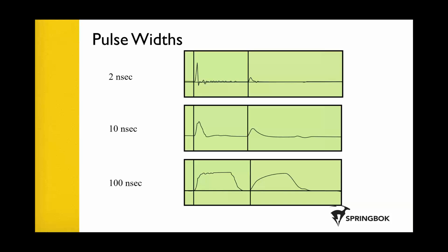If I give that rope a lot of energy, it's going to go a long ways, right? Versus if I give it just a tiny flick of the wrist, it doesn't go as far. So you could say that your larger pulse widths are for going longer distances or for testing longer lengths of cable, and your smaller pulse widths are for testing shorter lengths of cable. Also partially true, but there's a little bit more to it than that.